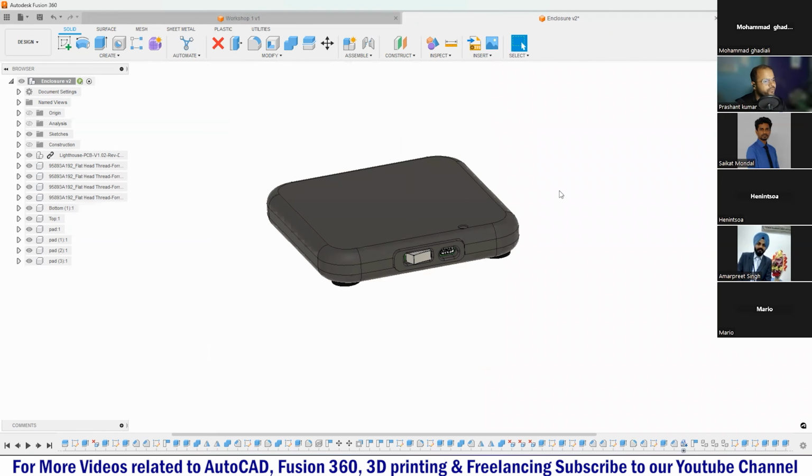Here you can see in the design tree, since we had created lots of sketches, a sketch folder got created. Since we had created lots of other stuff, all those things got created over here, right? So it's basically a tree that organizes your components, your parts, and your assemblies. And at the bottom, all the steps you had taken to create this complete design are getting recorded. So this is the area from where you can start editing your 3D models, right?